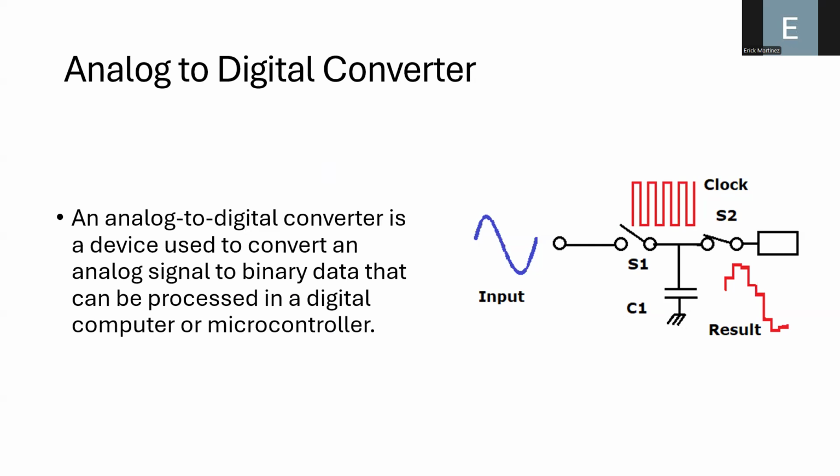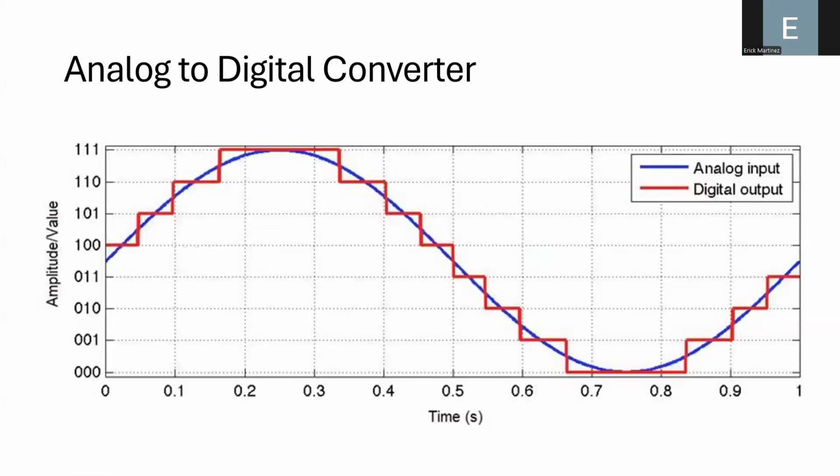At the end, we use this process because computers cannot take measurements instantly. They can be very fast, but they cannot take samples at the smallest amount of time possible. So what we need to define is a sampling frequency. That is the rate at which we take the measurements from the sensor, and we are basically producing a discrete representation of the original signal. But you need to be careful about this.